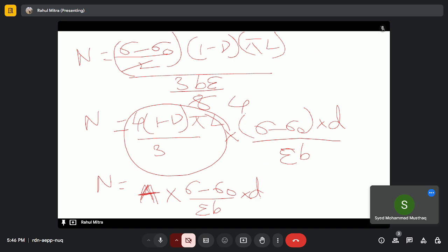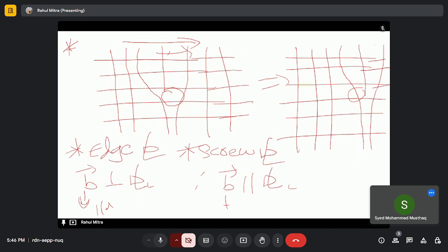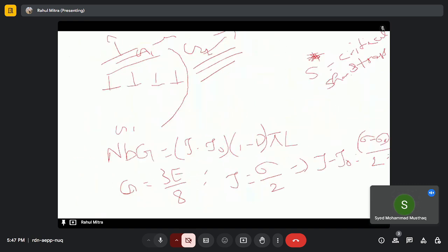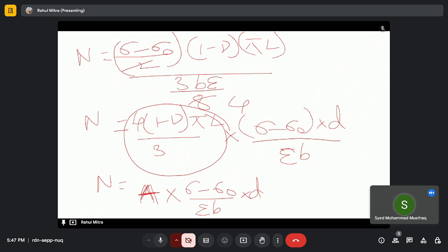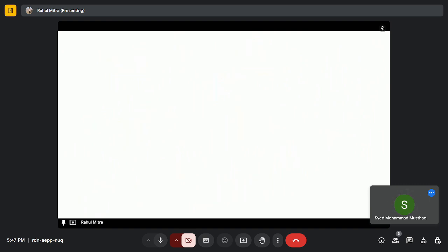Now, for the movement of dislocation from one grain to another grain, our shear stress should exceed the critical stress. So for all the dislocations combined, that relation will turn out to be n times tau minus tau naught times b should be greater than or equal to S star.